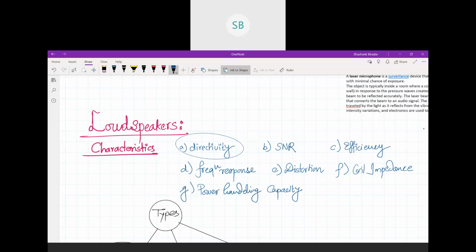What you need to do is put some source before the microphone, and rotate the microphone along the circle, from 0 to 360 degrees. While rotating, you calculate the output power produced by the microphone and plot that on a directivity graph, so that you can get the directivity pattern of the microphone.